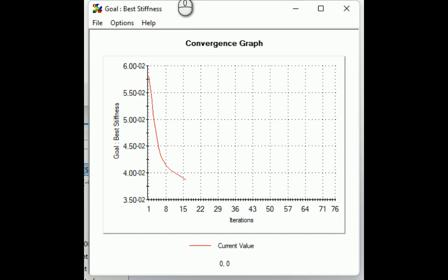Right? We can click on best stiffness, meaning that you can see this goes down, so it's going towards that goal, right? The goal here being the change from ratio to ratio. Remember when we did convergence? So that is what it's doing here. We'll go until it reaches our acceptable tolerance, meaning the change is so small that it is acceptable for it to say, okay, we could stop the solution, we are happy with the solution.